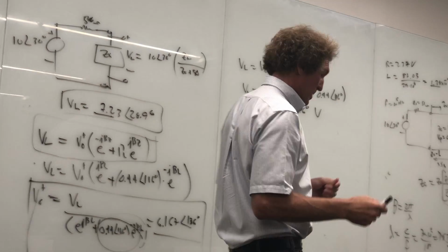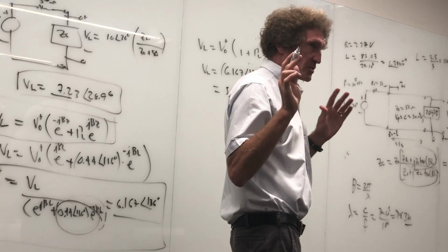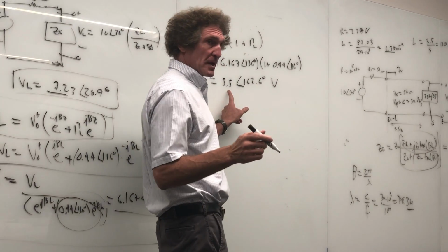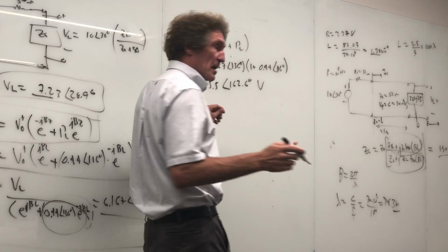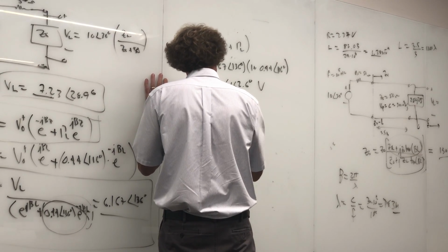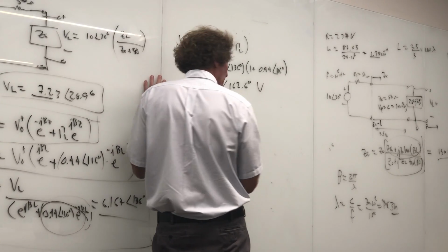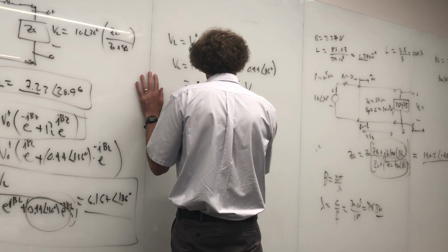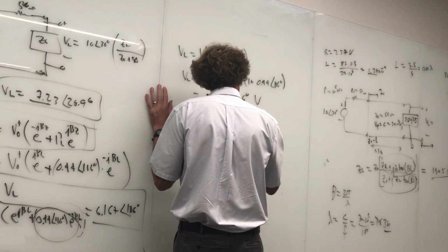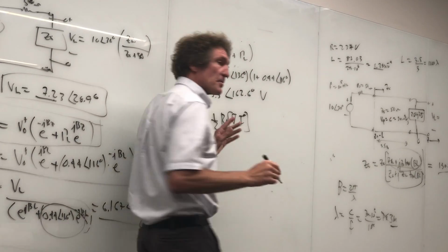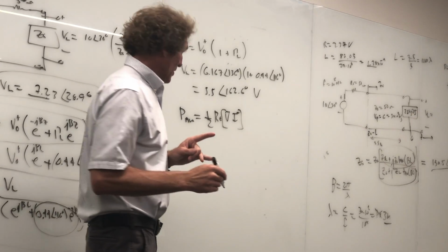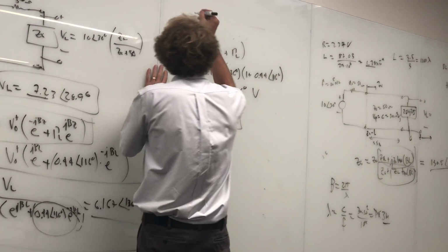Voltage over the impedance. Well, let's make sure everybody follows me on this one. This is a peak voltage here, 5.5 is a peak voltage. Now, to get average power, it would be 1/2 the real part of V phasor times I conjugated. You all agree with me there? V times I conjugated, we covered that. All right, so what is I?